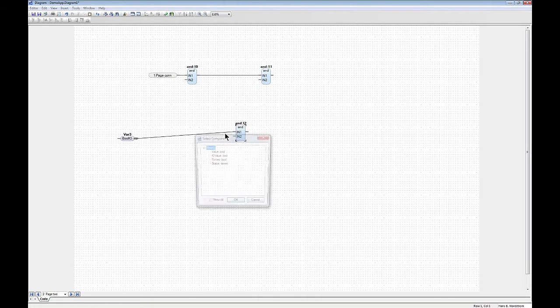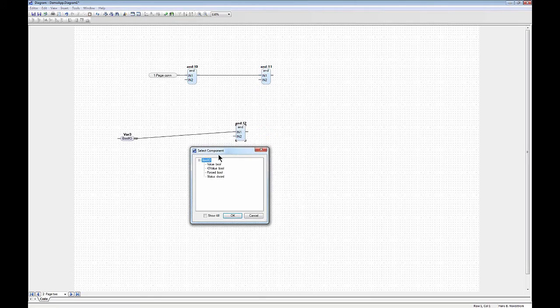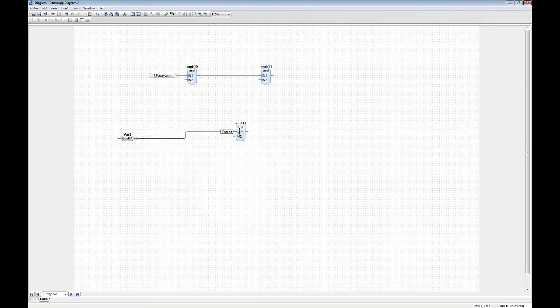But if I try to do it, I get an editor asking for what component did you want to connect to? Well, I want to connect to the forced value, for instance, in order to know if someone actually forced the I/O. And now I made a smart connection between the bool IO to the bool with a dot notation in between.